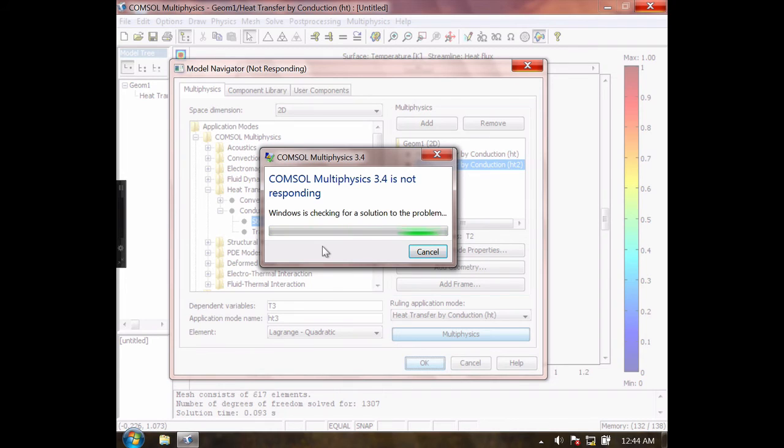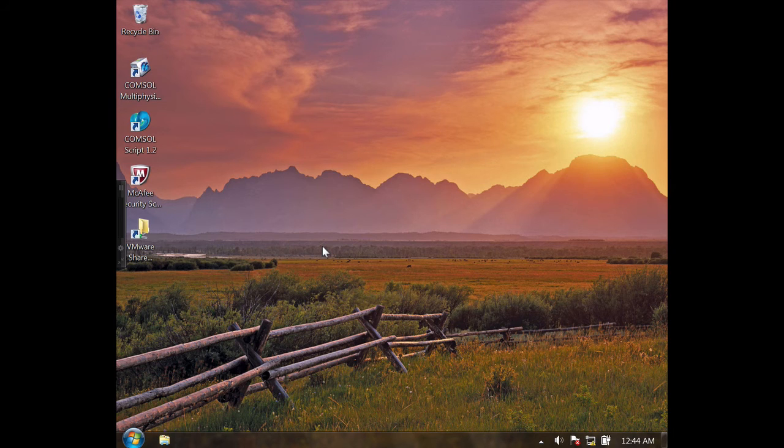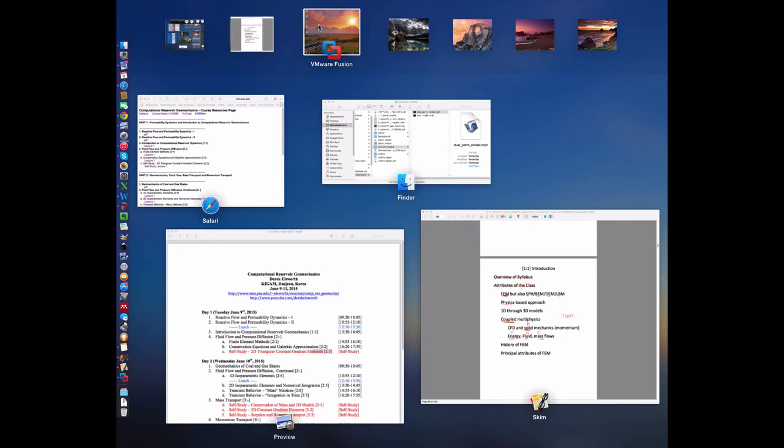So what it's done is it's taken this geometry with a hole cut in it, it's filled the whole geometry up with triangles which have completely filled the domain, and on these triangles it has tried to solve things in terms of the nodal parameters that are the vertices of these individual elements. And so what we need to do is find out how to put those things together. So that's our next task in all of this.